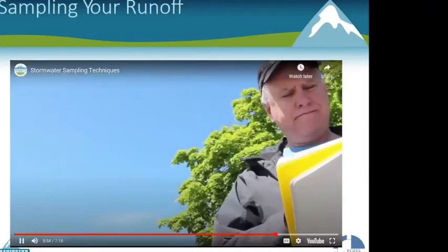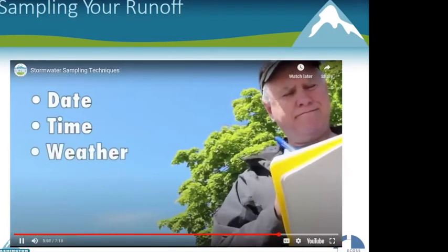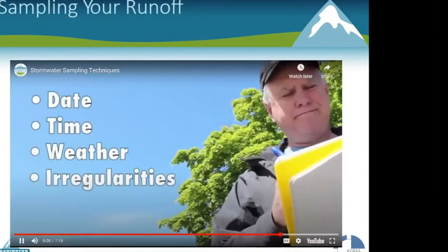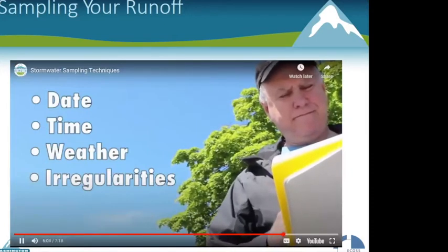Your sampling notebook should contain the date, time each sample was taken, and the weather conditions. In addition, note any irregularities at each site, such as strange odors, color of the water if out of the ordinary, or other abnormal conditions.